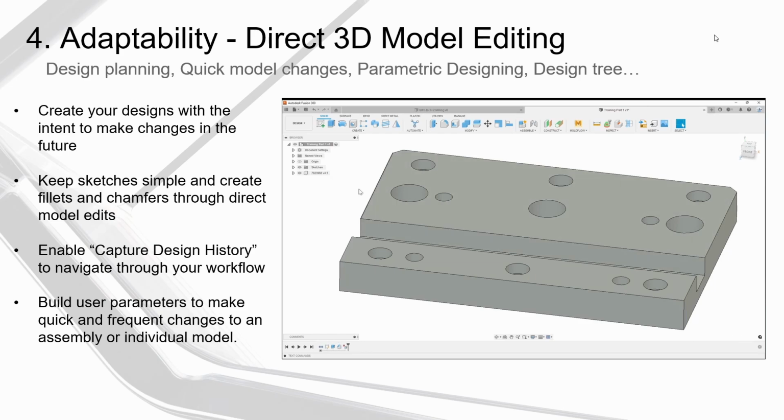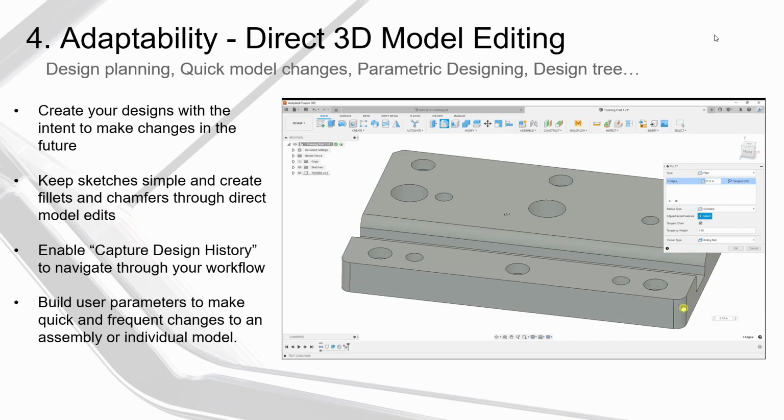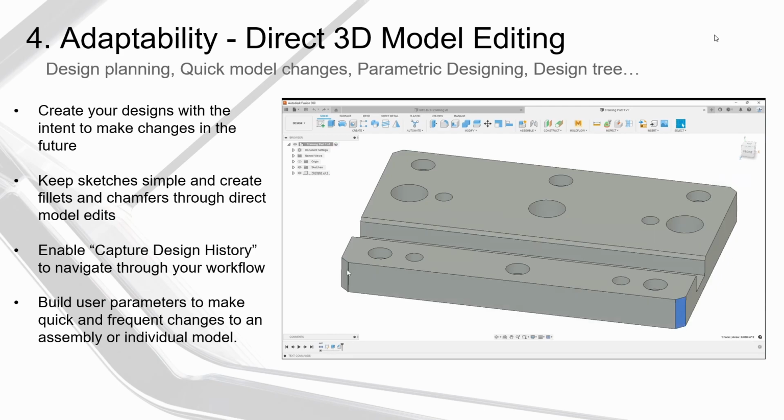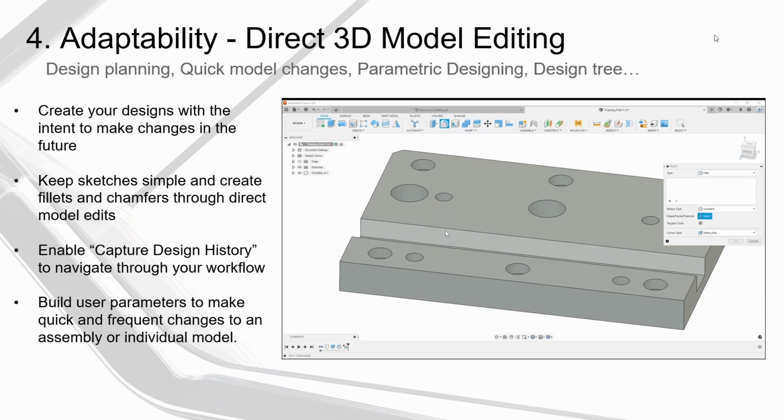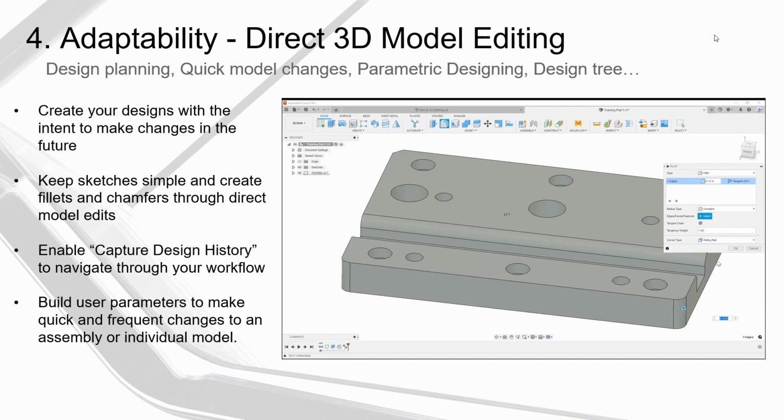Now, you can also go ahead and create your designs using parametric modeling on Fusion 360, which is nice because in case you knew that you had changes to be made to your part, or your part had multiple or different variations, then simply using the parametric features, you can quickly change dimensions or values of those specific features of your part.